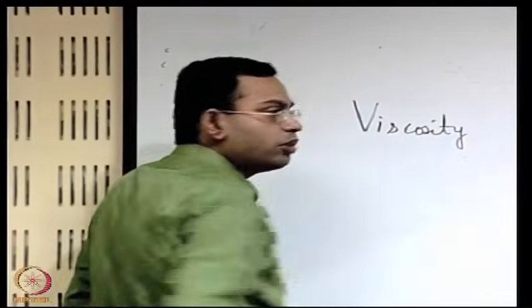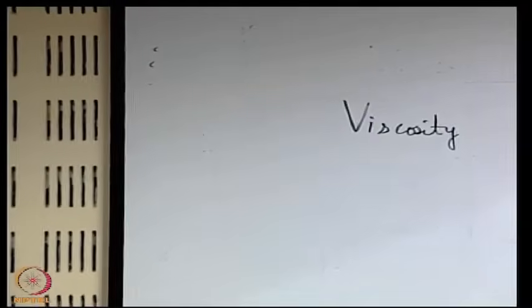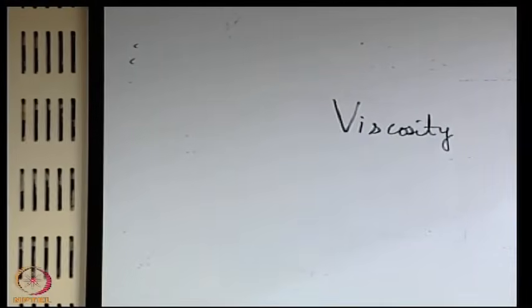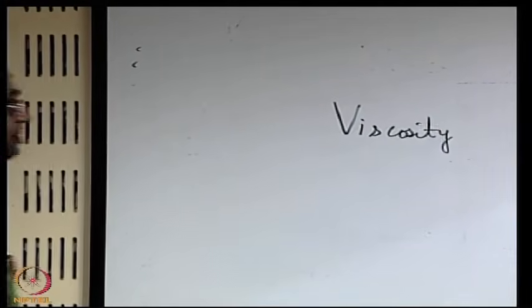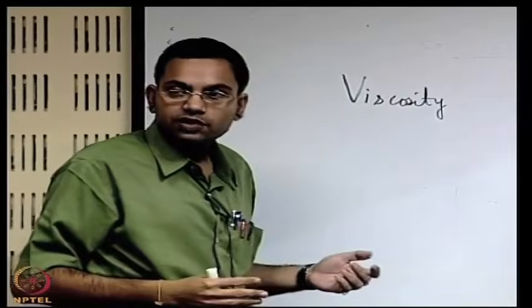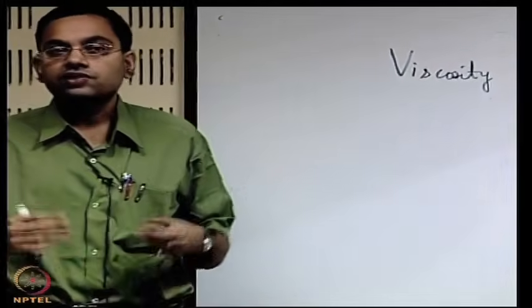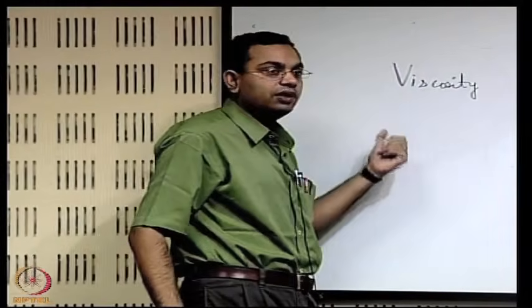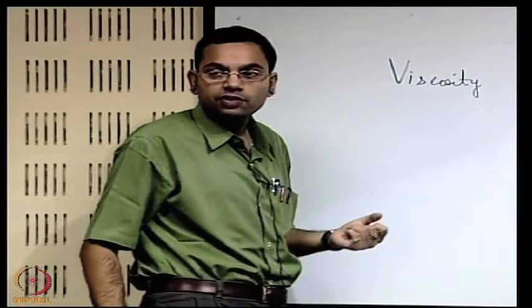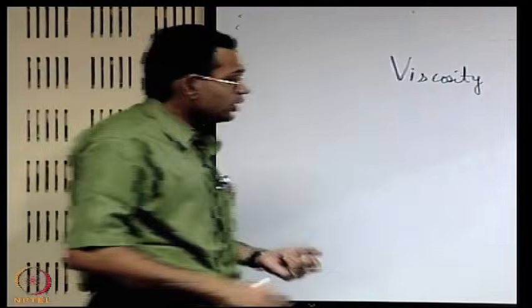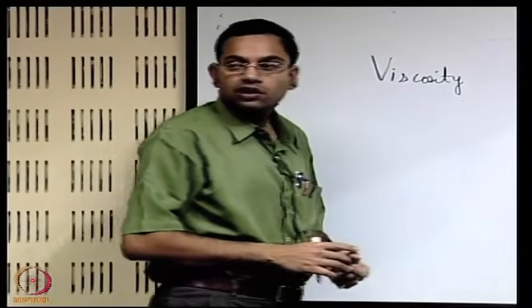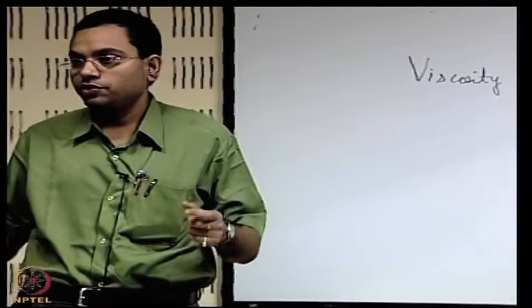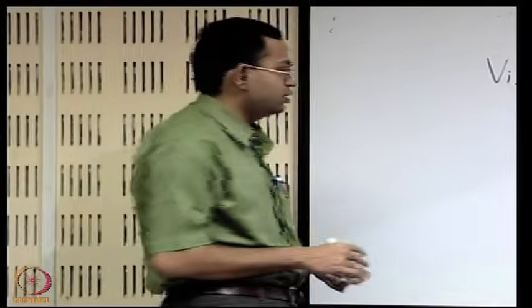which is a very important fluid property in the context of our discussions, and we will try our best to understand it first qualitatively and try to see how we can mathematically express the fluid flow behavior in terms of the fluid property viscosity. We start with recalling the no slip boundary condition that we were discussing in the previous lecture.